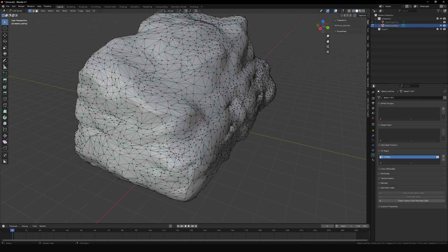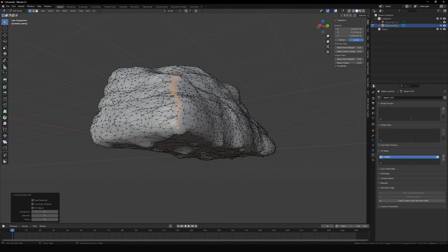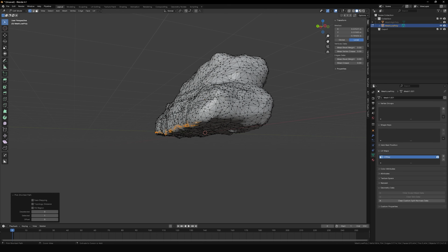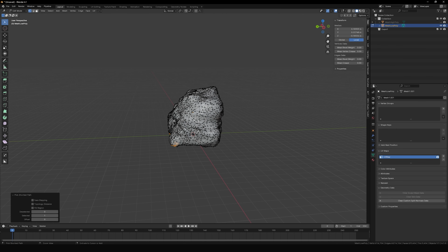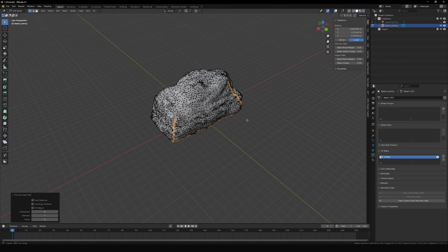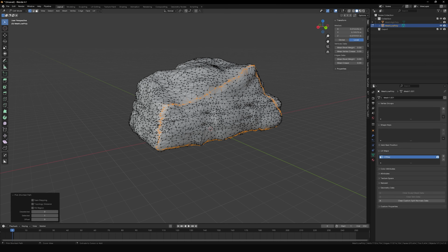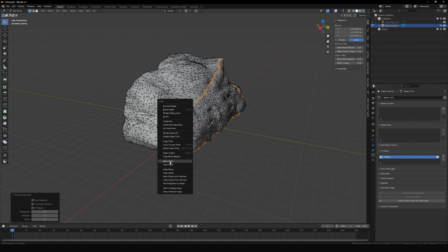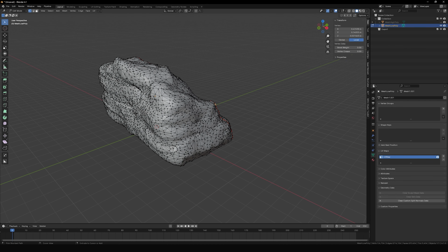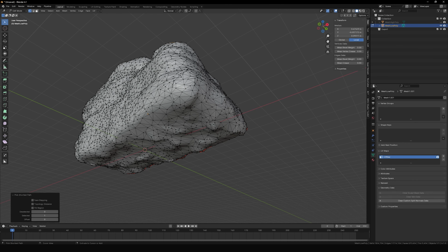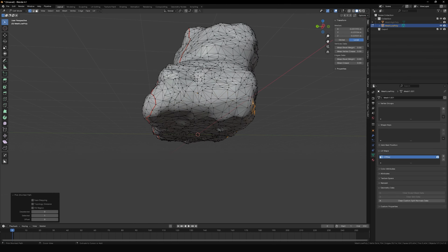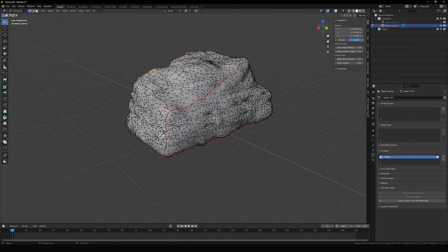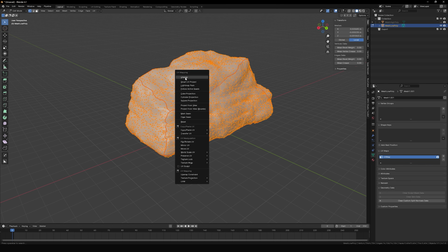This is fine. Let's deactivate the wireframe mode. And now we need to add some UVs to our low poly mesh. So I'm here selecting a vertex, holding Control and clicking. This will create this shorter line. This will take like a path, and let's mark this as a seam. It's a faster way to mark seams around your model, and since this is an organic shape, we don't need to be precise with this. It's fine like this, like a shape box. Press U and unwrap it.